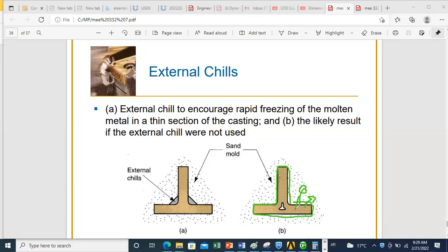This will lead to a more rapid solidification. This is why solidification will start from these zones towards the cavity. Because of this effect and because of reduction in volume, you might have formation of voids in the inner part of your cavity. To avoid this, you should encourage solidification in this zone, which is the critical zone here, because it's not interacting a lot with the outer environment.